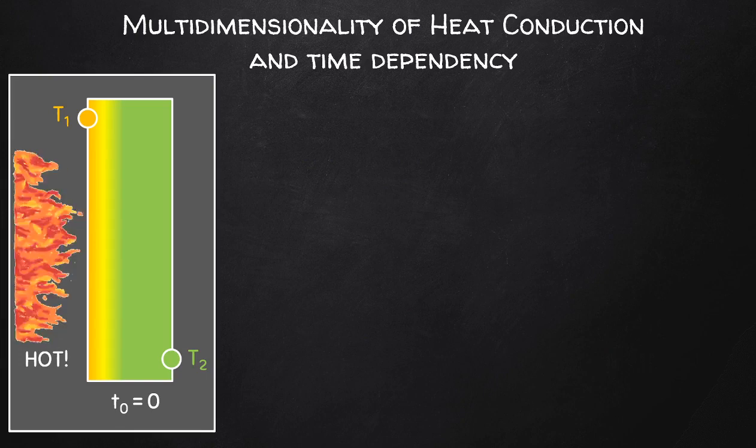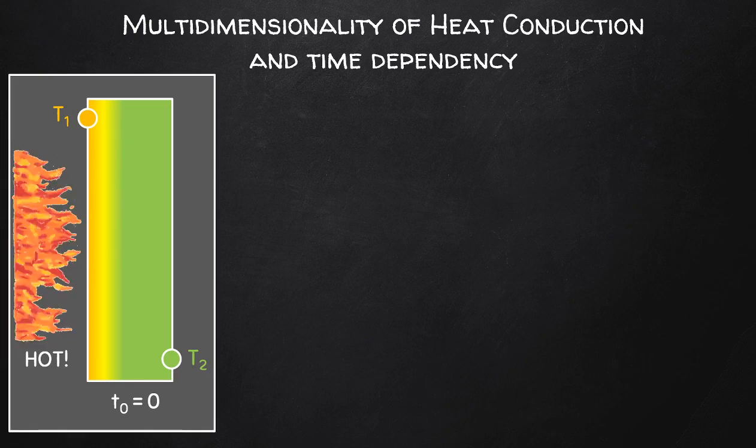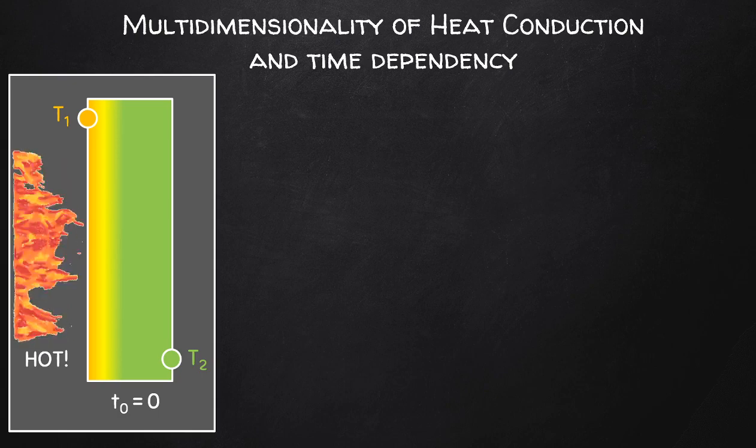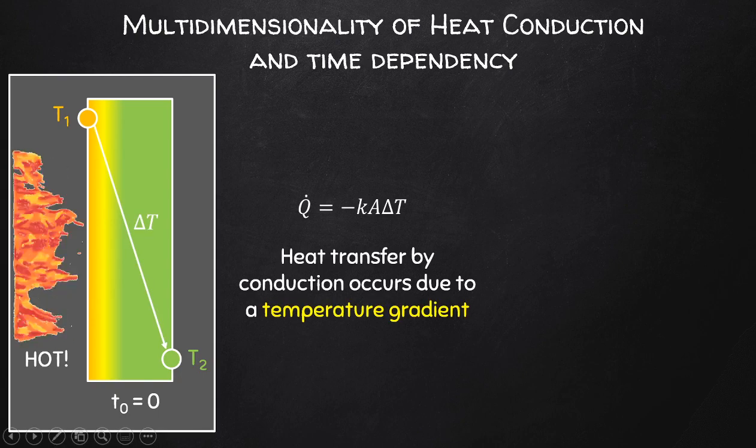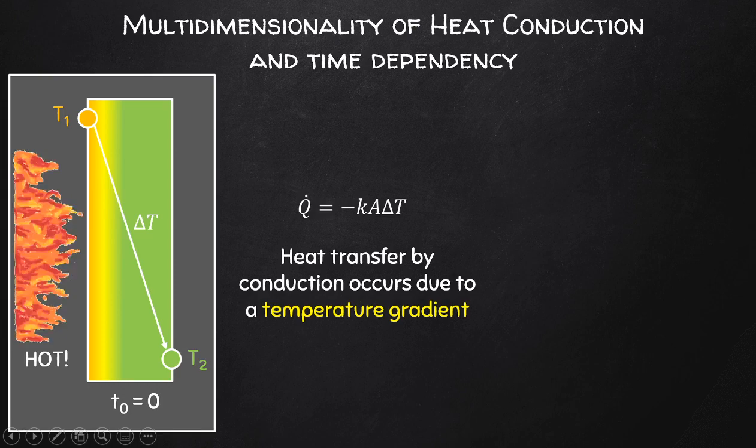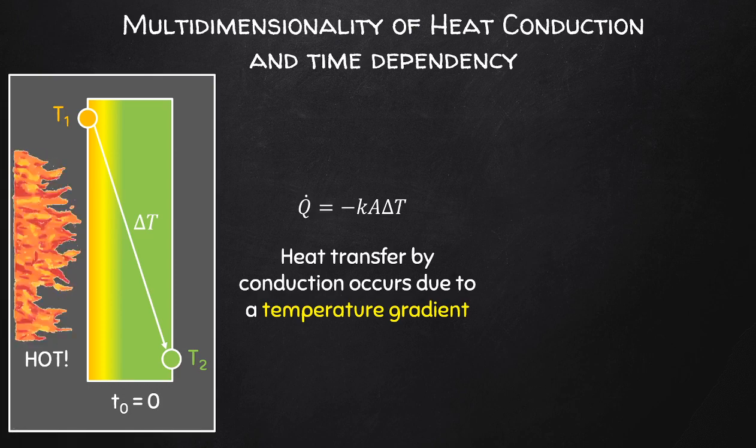Right, let's take a closer look at heat transfer through a rectangular geometry. As shown here, heat is transferred from the left side of the object, and this heat is then conducted through from left to right. The properties of the object in terms of its ability to conduct heat through itself is given by k, which is the thermal conductivity for the material, while the driving force for heat conduction would be delta T, which is the temperature gradient. The result is heat being conducted through an area that is exposed to the heat source, which is Q dot.